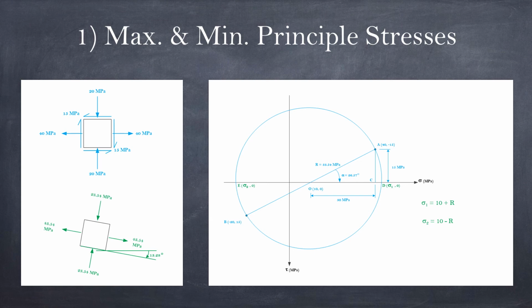But the element itself, as we already discussed, only turns half that, right? So if the angle in the stress plane is equal to 26 something, therefore, meaning we already turned the element by 13 degrees something, right? So to match the stress plane and the physical plane. And that's done. That's the answer for the maximum and minimum principal stress orientation.